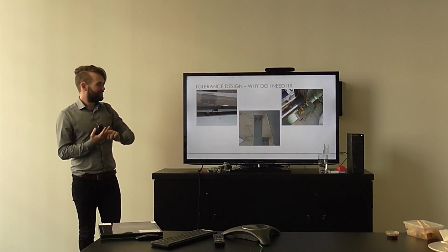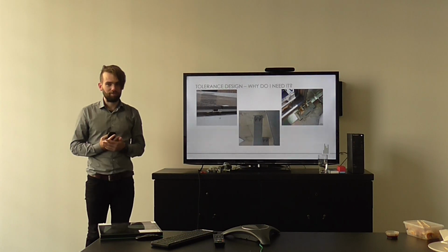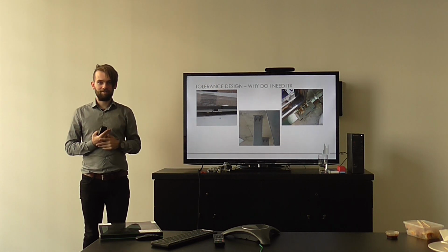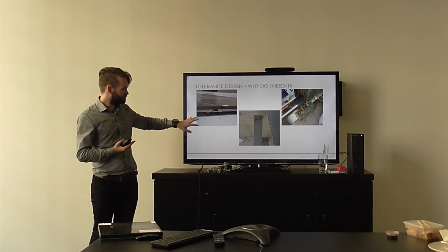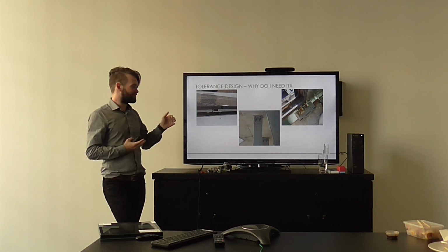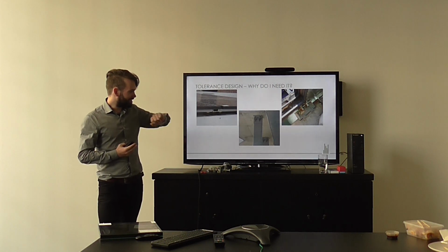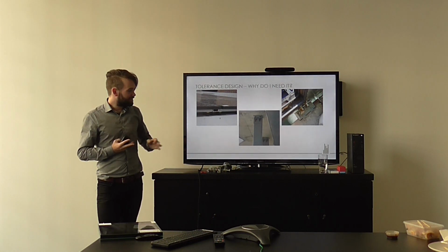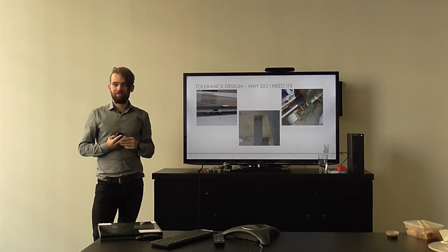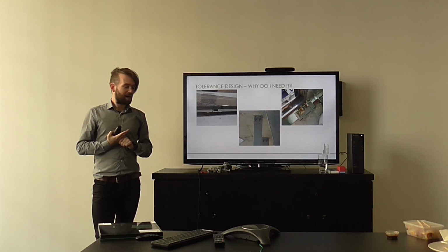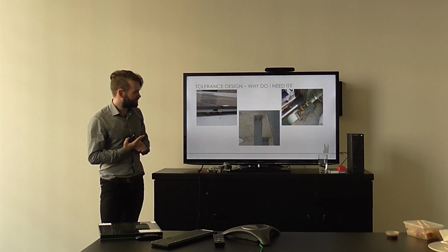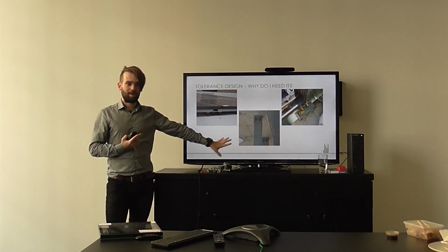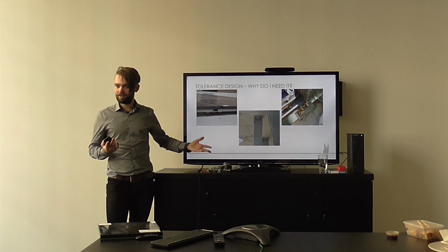What you can see on the left is a skylight job where the structural steelwork below is significantly lower than it was meant to be, so in order to get the glass line to where it needs to be, they've packed it up with probably 50 mil of pack, I'm not sure. The one in the middle is from a job where we're putting up some secondary steelwork to support glazing. This bracket is fairly well designed in terms of taking some tolerance, but the way it's been installed has resulted in it being completely hard up against the top of the bracket. So if by some chance the slab was deflected or moved down, that member doesn't have anywhere to go.